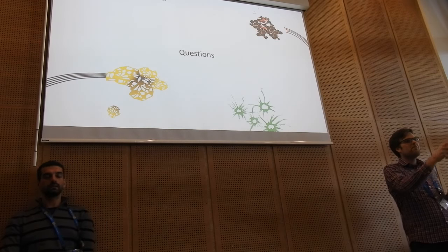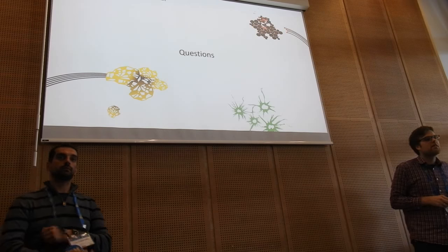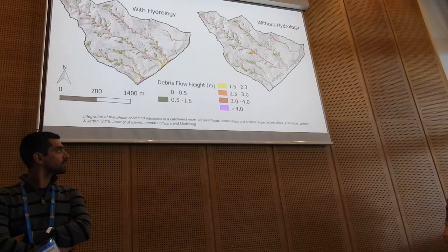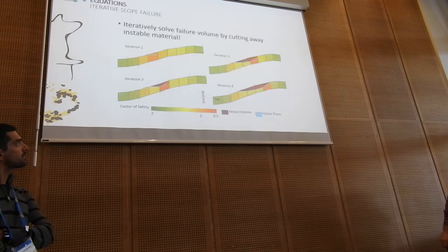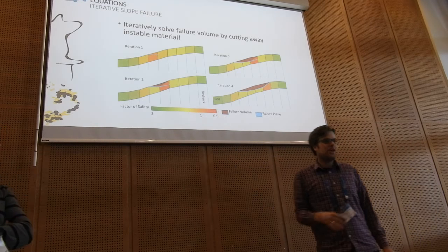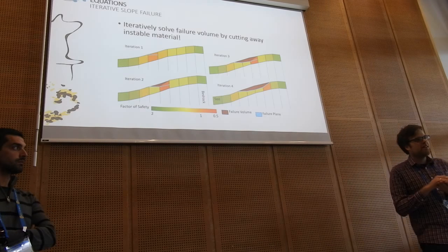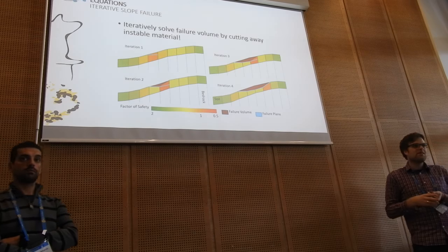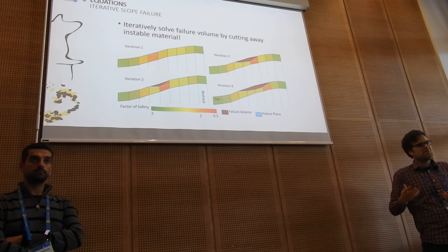So, how do you get from the slope model in 2D to a 3D volume? Oh well, it's quite straightforward to extend this to a 3D thing. Instead of checking the upslope cell, we just check all the 9 neighbors, and the slope for one specific cell is defined as the slope towards its steepest downslope neighbor. So yeah, we just extended this basically towards two directions.